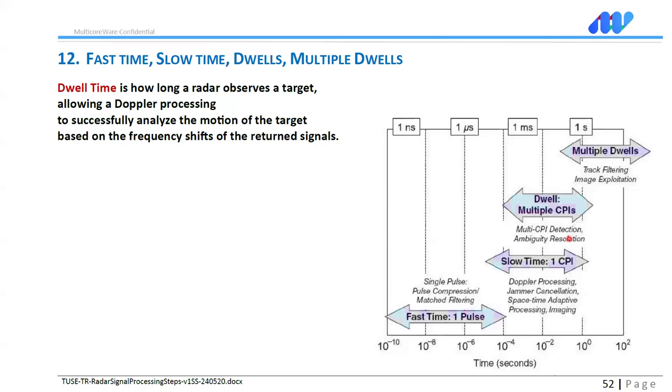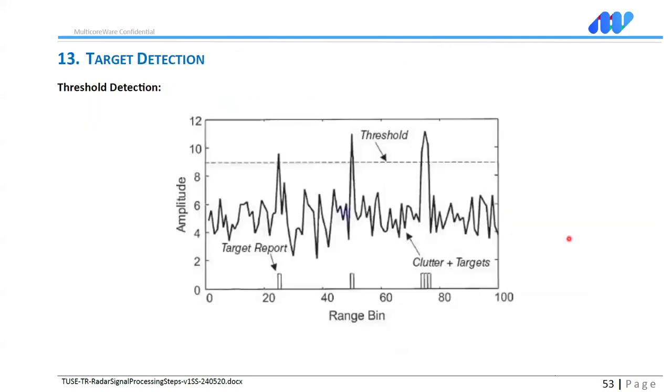So that's probably, for the sake of completeness, I will review the following steps, which is outside the scope of this presentation. So we're done. Beamforming is done. But what we do next is the target detection. And basically, you expect a very clean signal because you had 3 different gains applied to your signal. And now your signals should be above the average, above the noise level. And we call it the threshold, right?